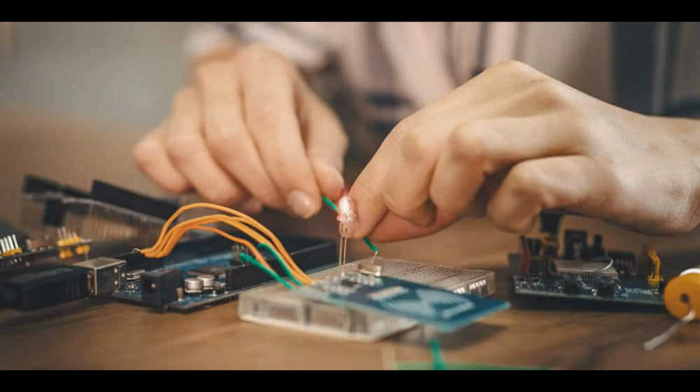Improved soldering. Solder mask defines the precise areas where solder should be applied during the soldering or reflow process. This helps ensure that components are correctly aligned and soldered to the PCB, reducing the chances of solder bridges, unwanted connections between closely spaced pads.